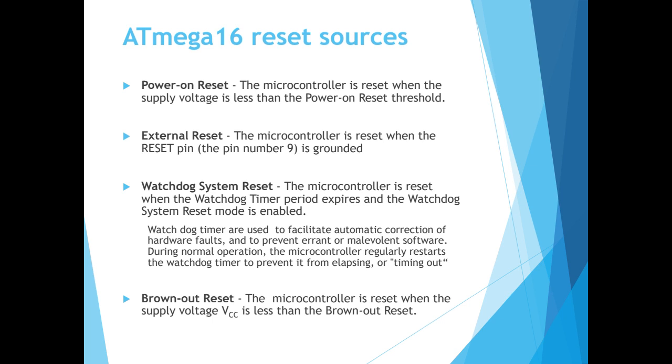The microcontroller is reset when the reset pin, which is pin number 9, is grounded. If you consider the microcontroller datasheet, the external reset pin number is 9, and for applying reset, it should be grounded.